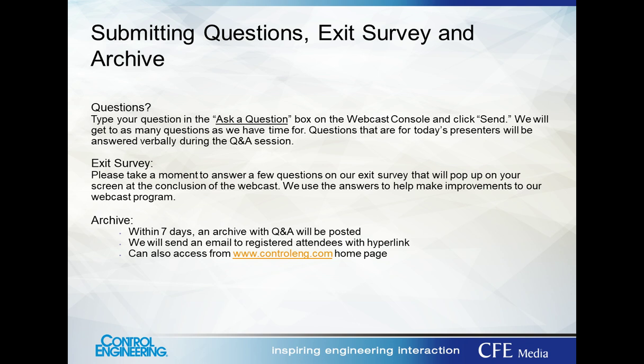And the other thing I wanted to mention on this, it was crossing my mind, that doesn't get a lot of attention is dead time. So dead time is another control technique that everybody should learn in the beginning because you see a lot of that, how it works, what you can do. And basically I'm talking about a Smith predictor with variable dead time. If you learn how to use that and you learn how to use feed-forward, that's a great start on being a control engineer.